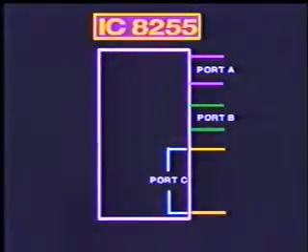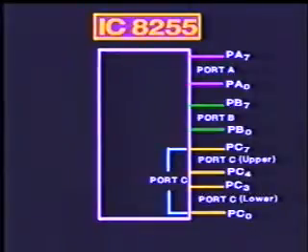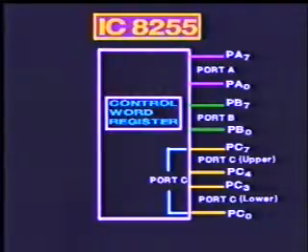The device features three ports named A, B and C. Each one of them is an 8-bit port. However, port C can be divided into two 4-bit ports and used separately. The device also has an 8-bit internal register to store the control word.